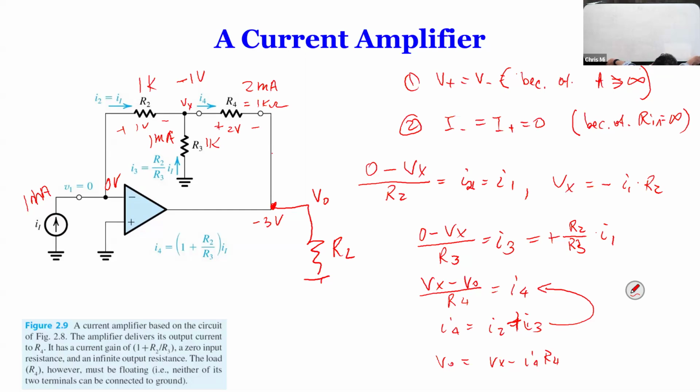That's a great explanation. A lot of signals in life are very weak, very small. Take a cell phone, for example. You receive through this little antenna some sort of electromagnetic waveforms, generating an output probably in the microvolts. You can't use it. It's too small. You cannot hear it because it's too small. What do you do? Use a bunch of amplifiers. You amplify 1 microvolt to much larger, eventually a few volts. And those few volts go through a speaker or something that you can hear. So we need to amplify.